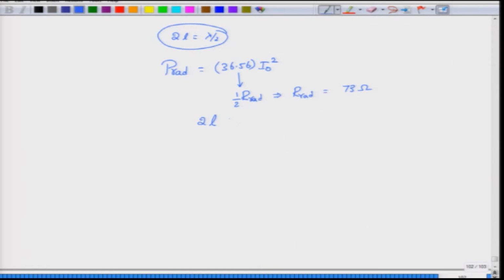Now, as I told you, as I increase the length, so let us say I take this length greater than lambda. Okay. So, in fact, I will take this one to be equal to 3 lambda. Okay. The overall antenna length has now increased to say 3 lambda. Then what you find as a pattern, you can actually use a nice MATLAB function to plot all this, or you can just write a small script to find out what would be the pattern by varying the angle theta, and you will find an interesting antenna pattern. So, you will find something like this. Okay.